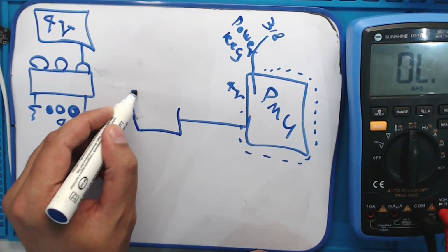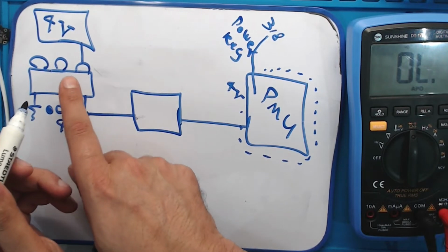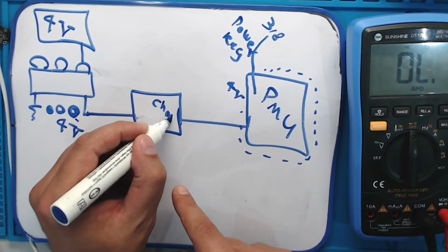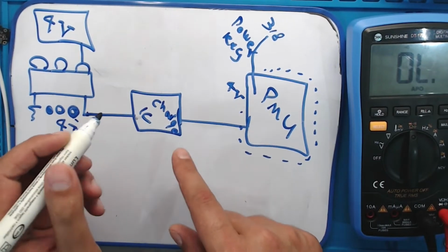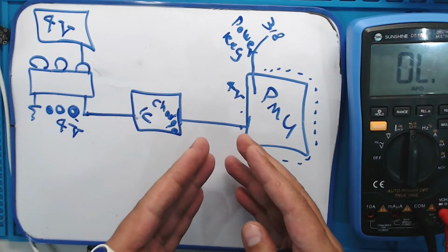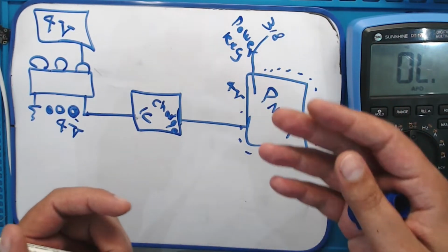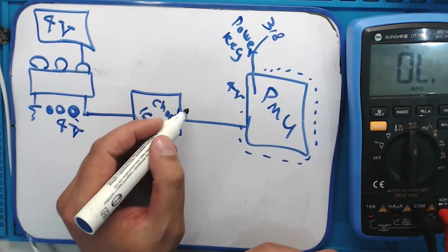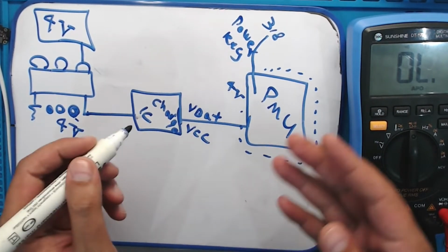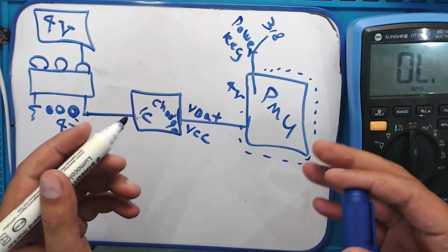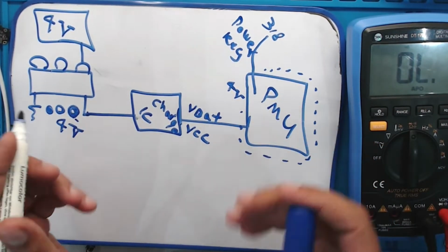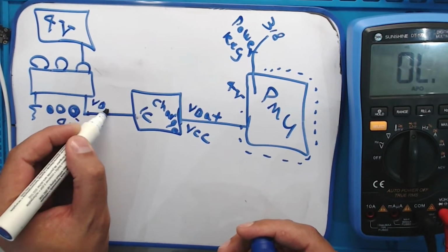On the smartphone, this battery voltage comes to the charge IC and changes form, and the output voltage has a different name. For example, we say VBAT or VCC or VDD main or VPH, just a different name and different circuit, but it's the same. That side is V battery.